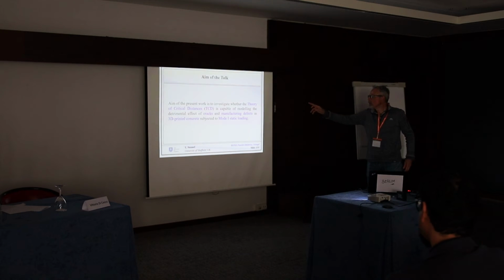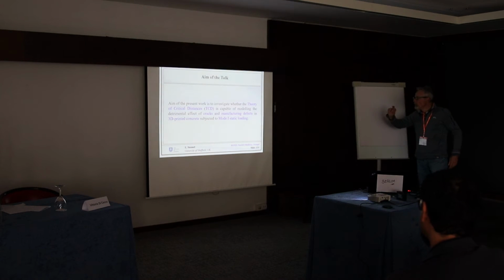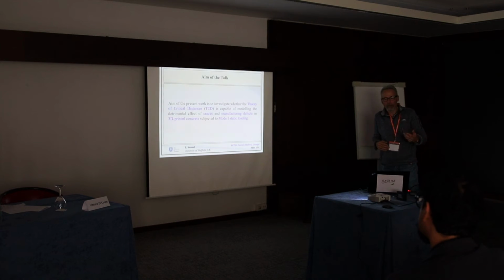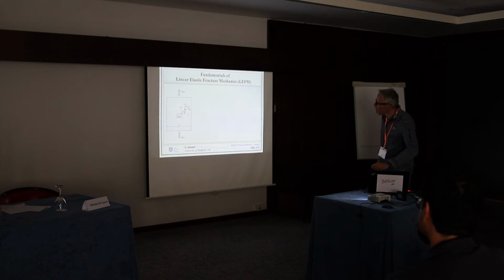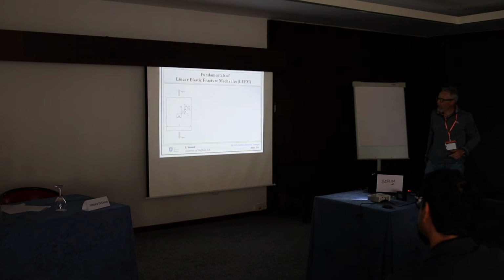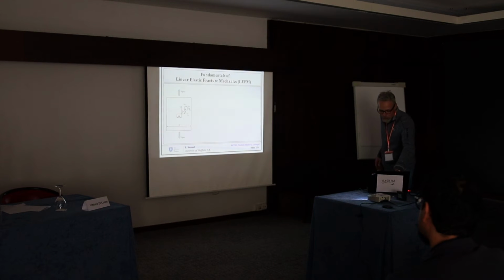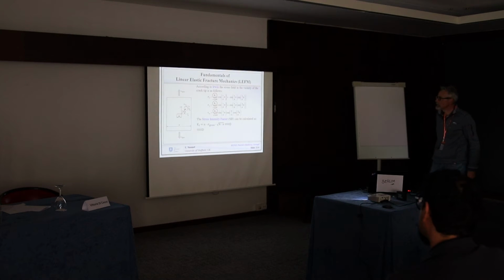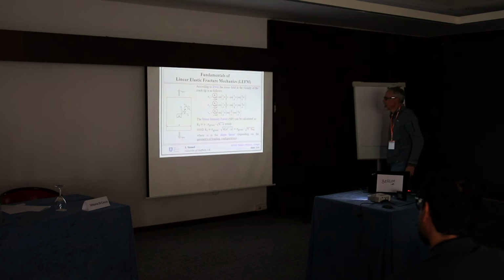And what we are going to do is to use the so-called theory of critical distances. So basically we are going to introduce a length scale parameter into our modeling. Okay, so let's go back to the fundamentals. So we have linear elastic fracture mechanics. We know that around the crack we can describe the distribution of the stress using Irwin's equations, and we know that everything is proportional to the stress intensity factor.